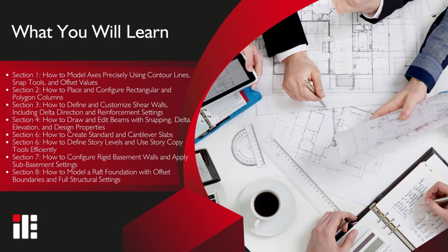In this tutorial, you'll learn how to model a complete reinforced concrete structure in ideCAD Structural, from axis definition to raft foundation creation. We'll start by placing axes using snapping tools and contour lines for precise alignment. Then, you'll see how to model rectangular and polygon columns, and configure each with accurate dimensions and materials.